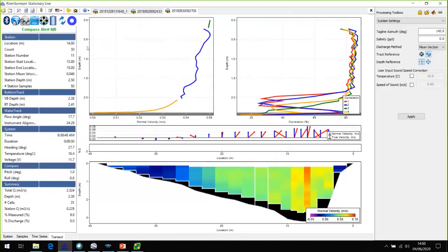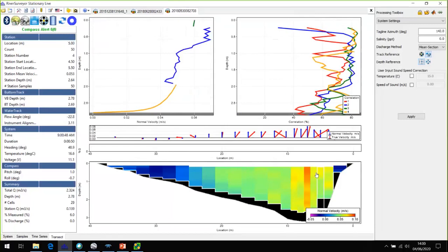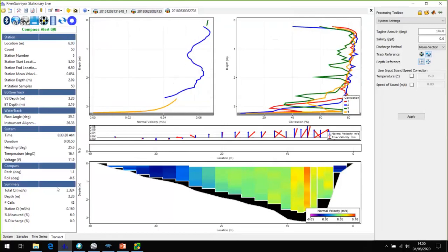The vectors in that graphic that we're looking at the moment look quite wayward, especially those 2 that are crossed. They're going all over the place. Yeah, that's what I mean about the location. If you look at my flow, it's 2.3 cumecs for the River Findhorn. It's pretty madly low. I think it's about the lowest ever got, actually.